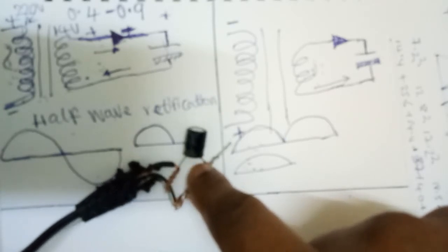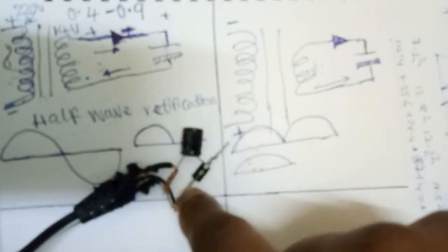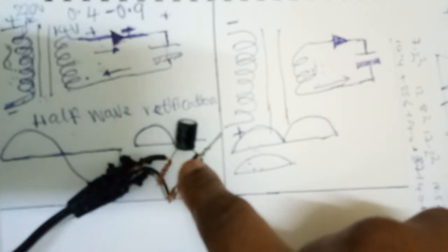What the capacitor does is to purify. This diode changes the AC to DC, and the capacitor will purify it, remove impurities, and make it smooth. When this diode converts AC to DC, the capacitor will make it smooth, because the DC from the diode is a pulsating DC. Pulsating DC means DC that contains ripples.